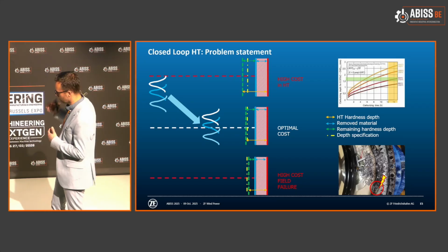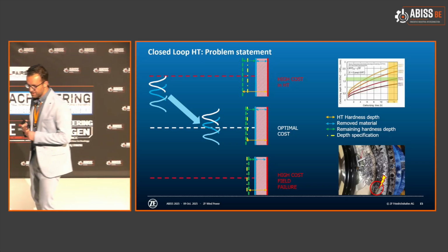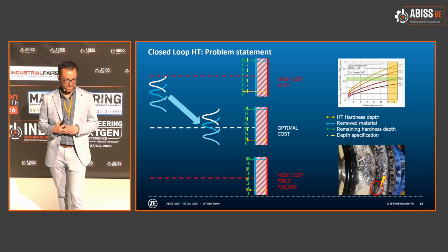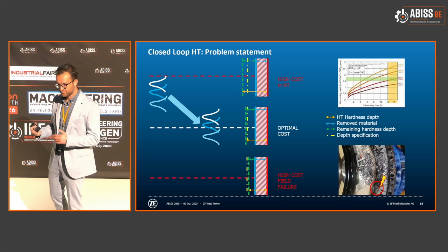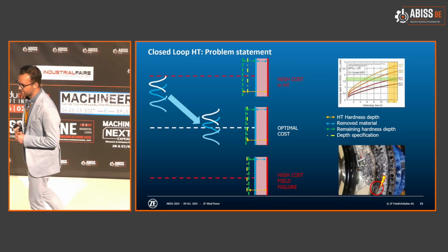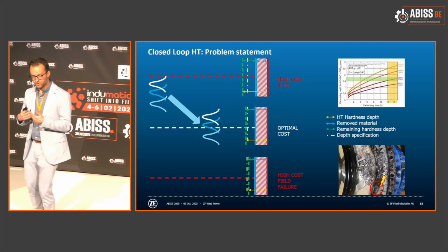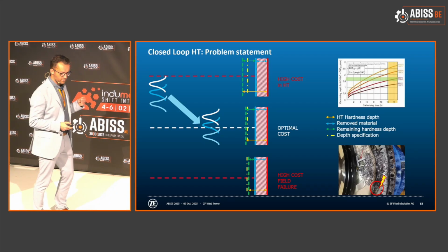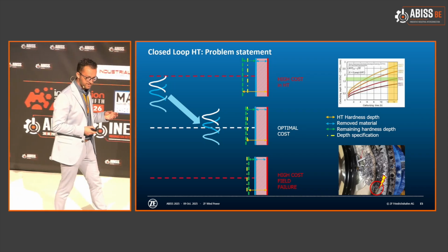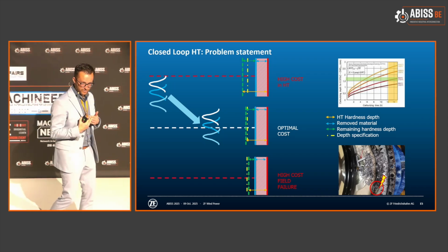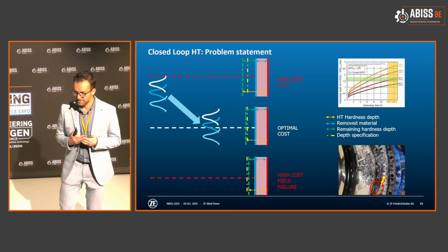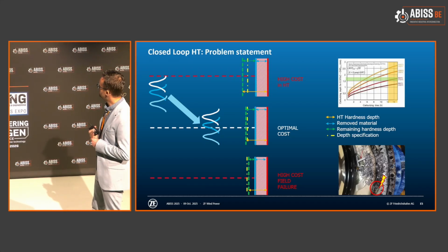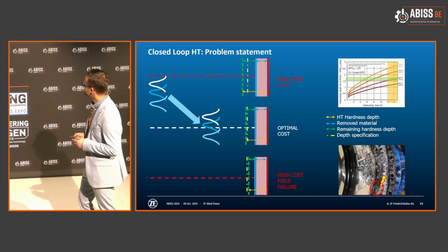So the yellow box here is an indication that for half a millimeter extra, it takes 3 hours extra, while in the beginning, in 3 hours, you have more than a millimeter of hardness or carbons in your surface. So it is really important. The longer you make your heat treatment process, the deeper the green line will go into your material, but it takes you exponentially longer to achieve those deeper values.